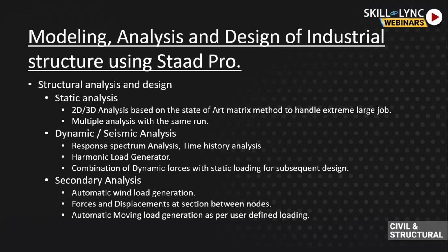And further, you can have a wind load generation. It has already got built-in wind definitions in Staad Pro. That will be very easy for carrying out the secondary analysis. And you can even calculate the displacements, forces, moments inside a particular structural component. And moving load generation for the crane loads is also possible through Staad Pro.